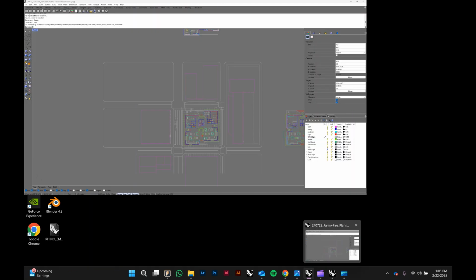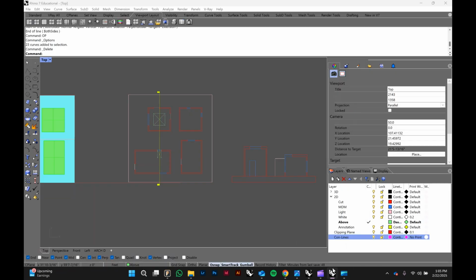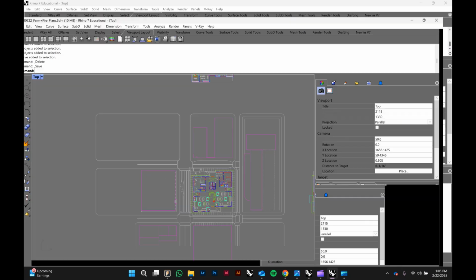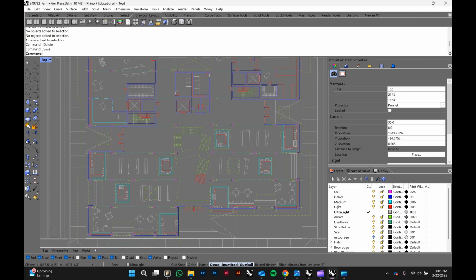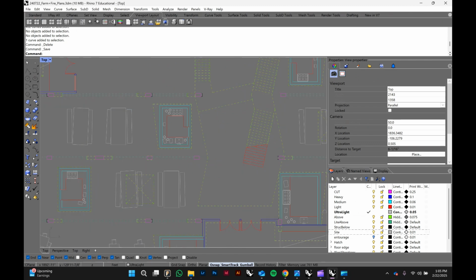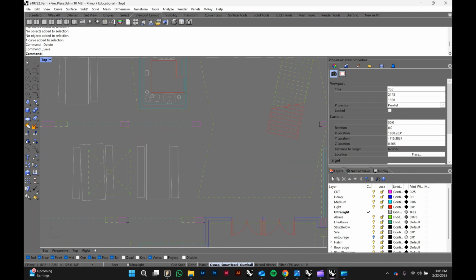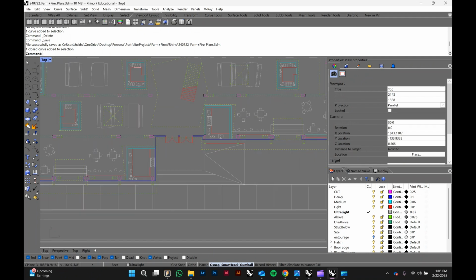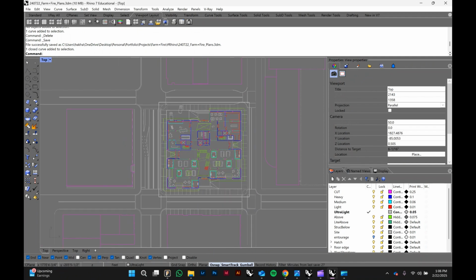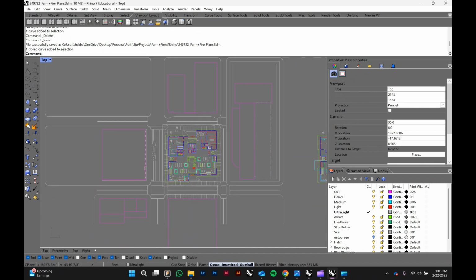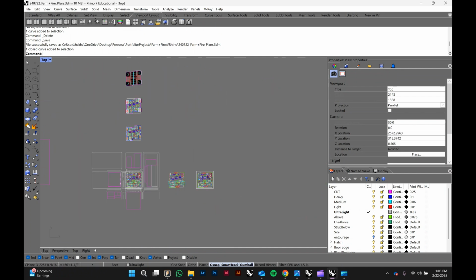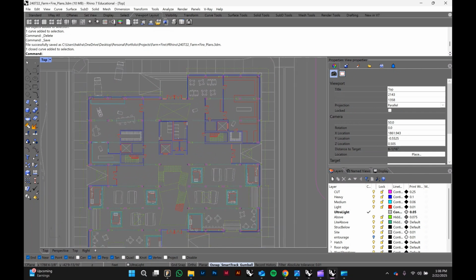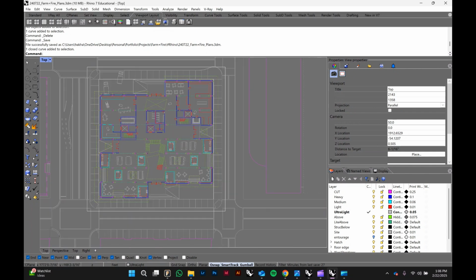Like I said earlier, I was going to pull up some plans that I've been working on, some old projects, but you can start to see the amount of information that starts to get layered in to really start to sell the plan and to give life to your drawings. So creating different layers for line weights is kind of imperative, and that's going to happen everywhere. But then also different layers for entourage and context and cutting through your site context. So it's really like this drawing started as a Make 2D, and I think I have some previous versions on here. But the Make 2D doesn't give you all of the information. You have to come in and kind of draw it out.